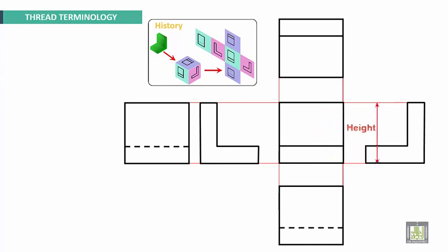This is the height. It is the same for the front view, which means elevation, right side view, left side view, and rear view. Here we have the width. It will be the same for top view, front view, and bottom view. And here we have the depth. It is the same for top view, right side view, left side view. Okay.